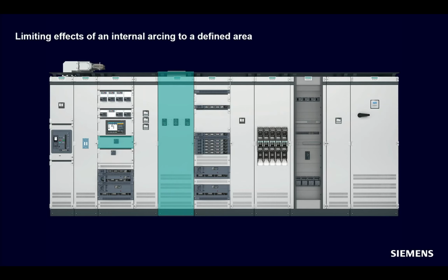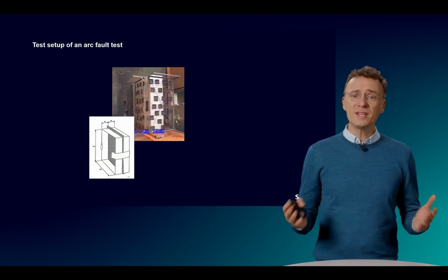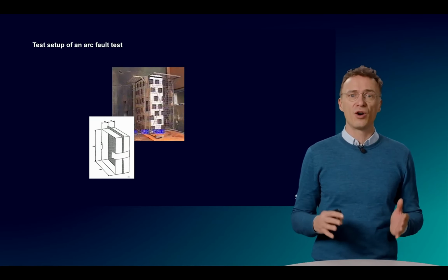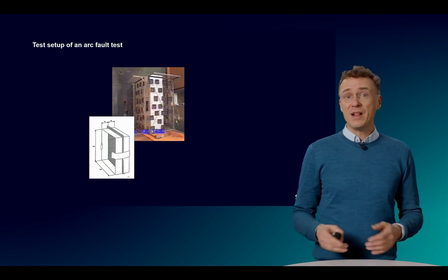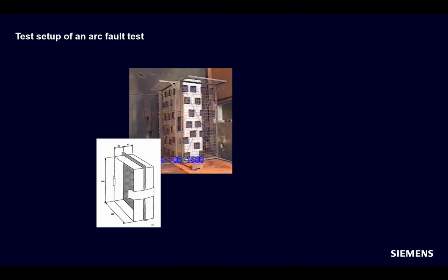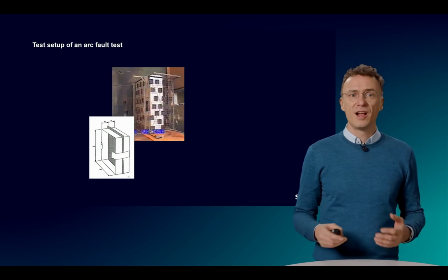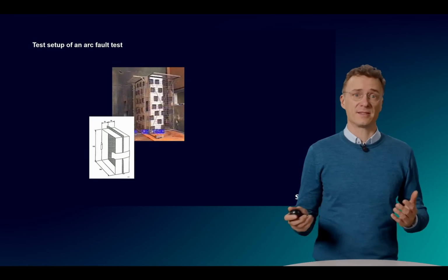Perhaps first a few words about the test arrangement. There's a grid standing in front of the test specimen. Attached to this grid are small rectangles of fabric, so-called indicators. These indicators are intended to simulate the clothing of a person standing at a short distance, approximately 30 centimeters, in front of the system. Two different fabric qualities can be used. A lightweight cotton fabric designed to replicate unrestricted access, like in leisure wear, or a heavy fabric of around 150 grams per square meter that represents the work clothes of staff with limited access.